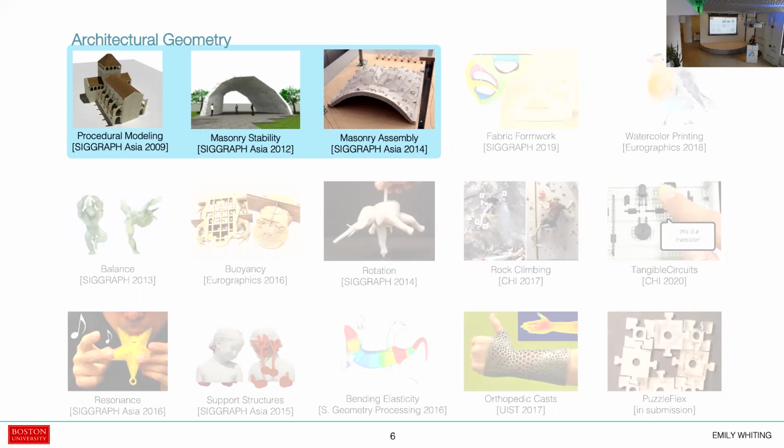This is a hierarchical method of defining an architectural style that can be done grammatically. And we looked at ways in which properties of feasibility, so that you actually have, say, structural static equilibrium, can be embedded into the rules, so that everything you create is actually a feasible structural building.